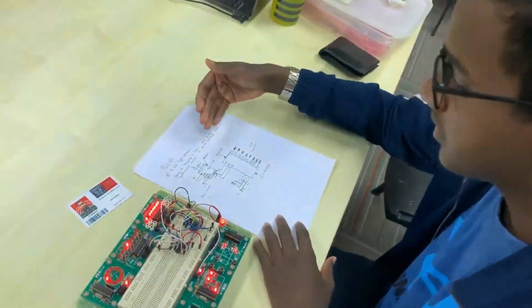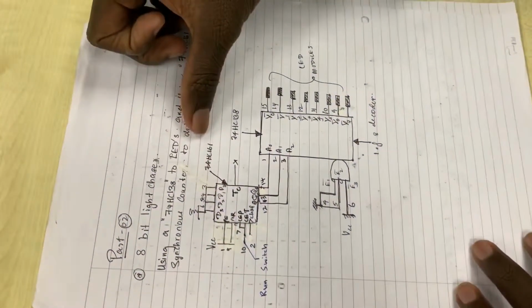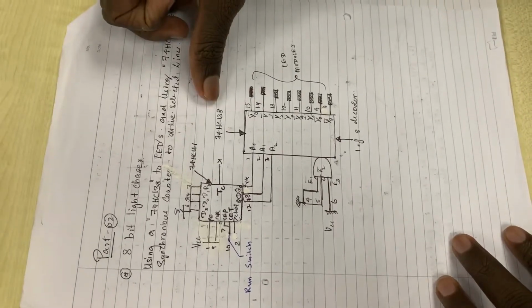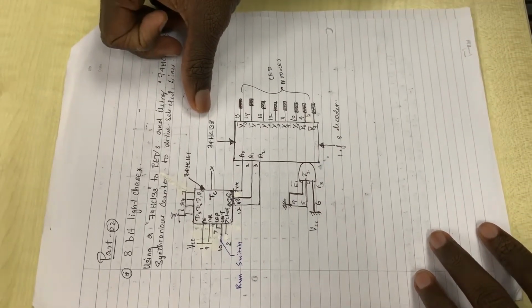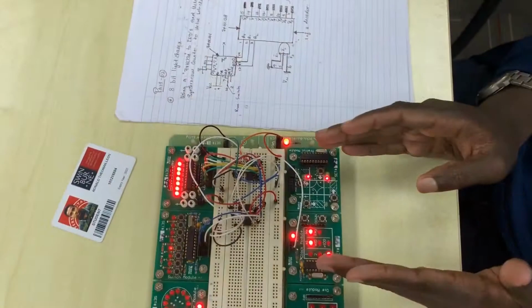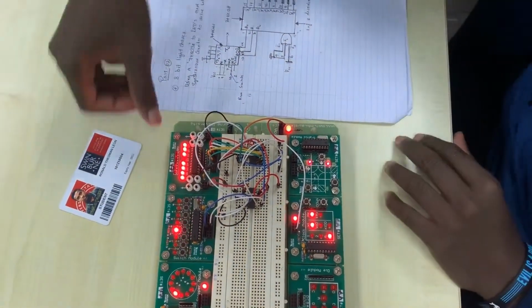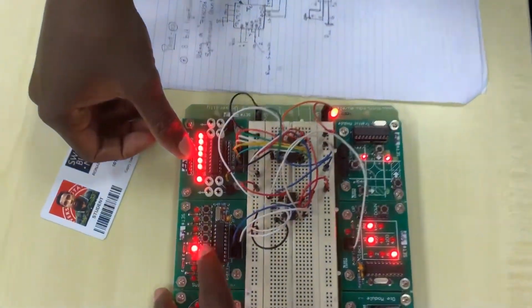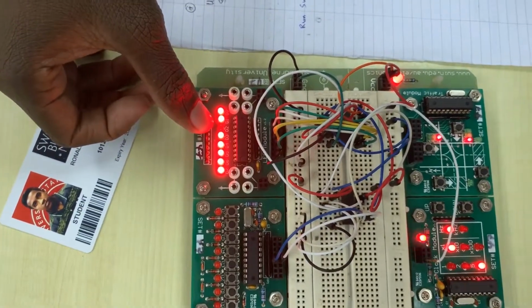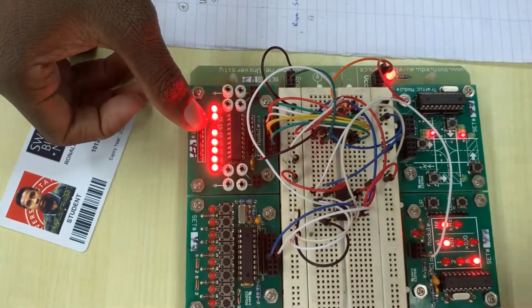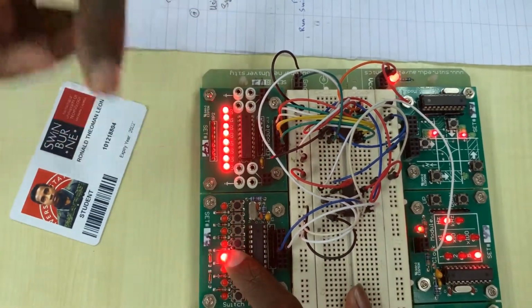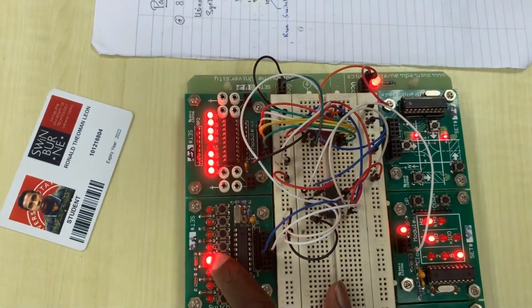So as shown below, the circuit has been built using two ICs, the 74HC161 and the 74HC138. Both the ICs have been lined up together side by side so that the output can be seen through the LED shown below. When the switch is pressed off, the circuit is in idle, and when the switch is pressed in, the circuit demonstrates the expected outcome.